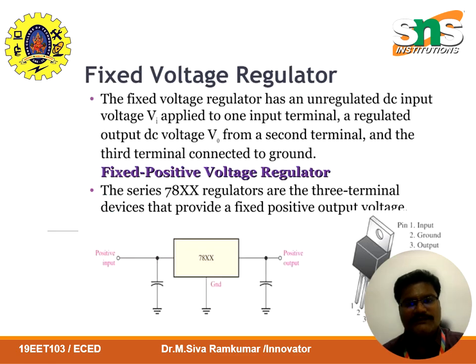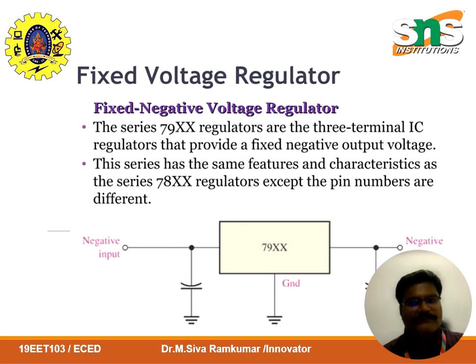One of the most commonly used components is the fixed voltage regulator. This regulator takes an unregulated DC input and gives a constant DC output. The popular 78XX series has three pins: one for input, one for output, and one for ground. For example, the 7805 gives a fixed plus 5 volts DC. It's simple, reliable, and great for powering microcontrollers.